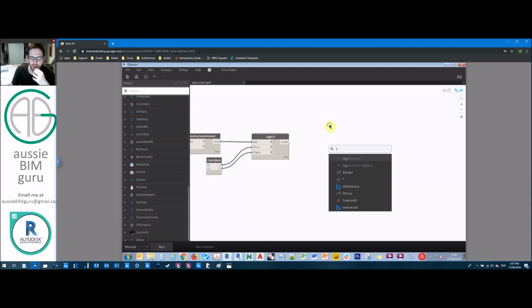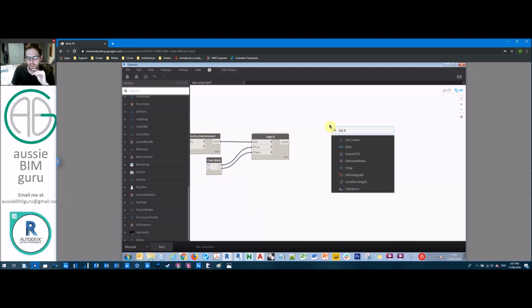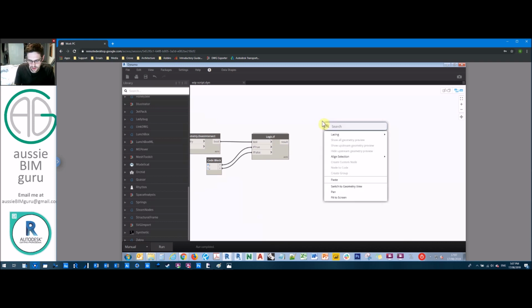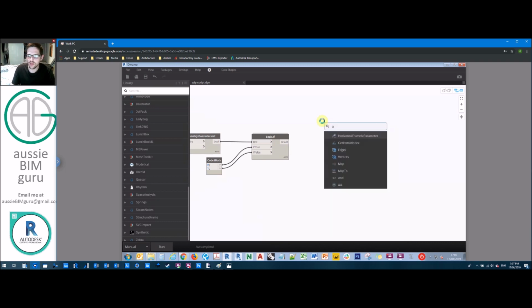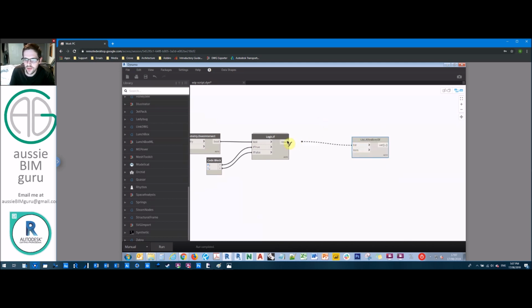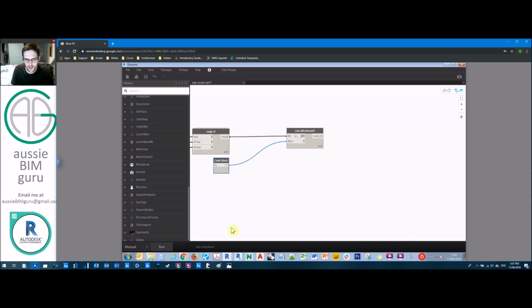So we're just going to look for all indices of, sorry, my search function in Dynamo is incredibly slow today. I think because I'm handling so many results, it's just slowing everything down. So bear with me. Okay, so we're doing all indices of, and we're going through each sublist. We're going to work at level 2 in our list, and we're going to look for 0. From these indices, we're going to be able to process positions to break our lists at. You can see that we're finding the indices in each list where a 0 occurs.